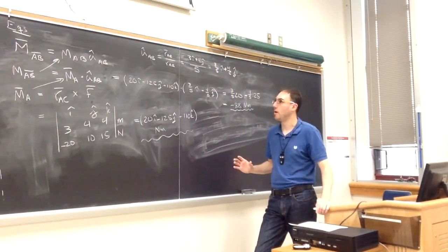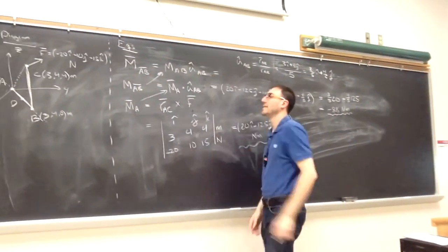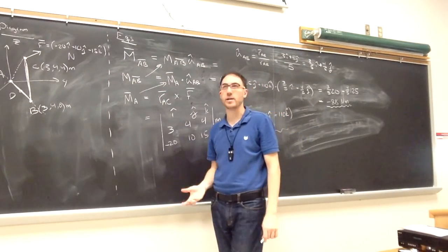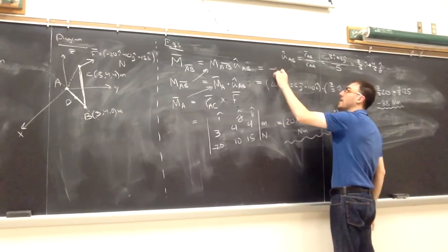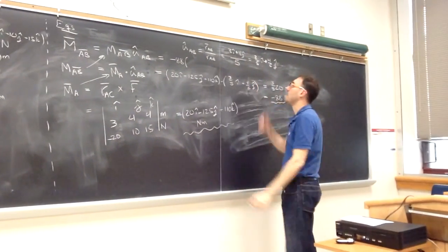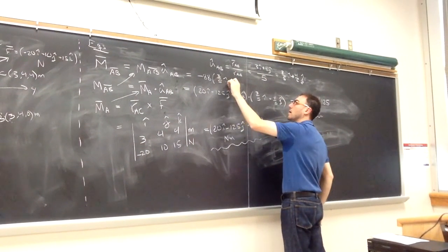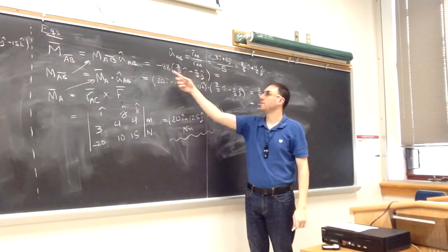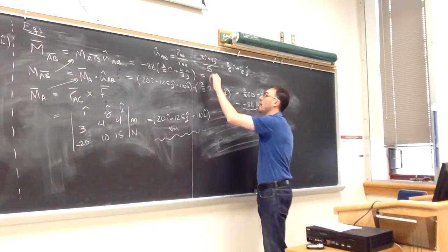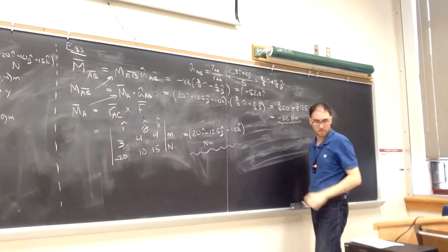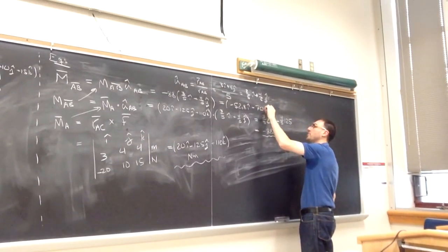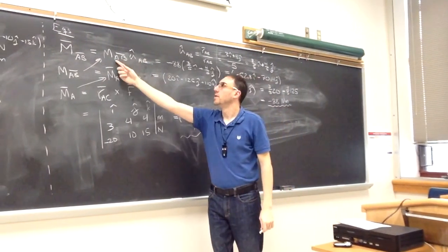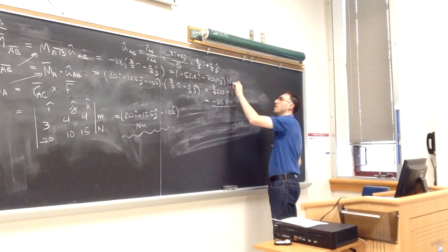Right, so I have the magnitude of the moment around that axis. I can go up one more level because I now have the moment around AB as a magnitude. So the last step is, if I want my answer in Cartesian component form, I multiply what I just found, the negative 88, times U hat AB. I have a scalar times a vector, so I can just distribute that negative 88 into it. I'll get negative 52.8I minus 70.4J. And the units, since this is a unitless quantity, the magnitude of that moment was in Newton meters. This is also in Newton meters.